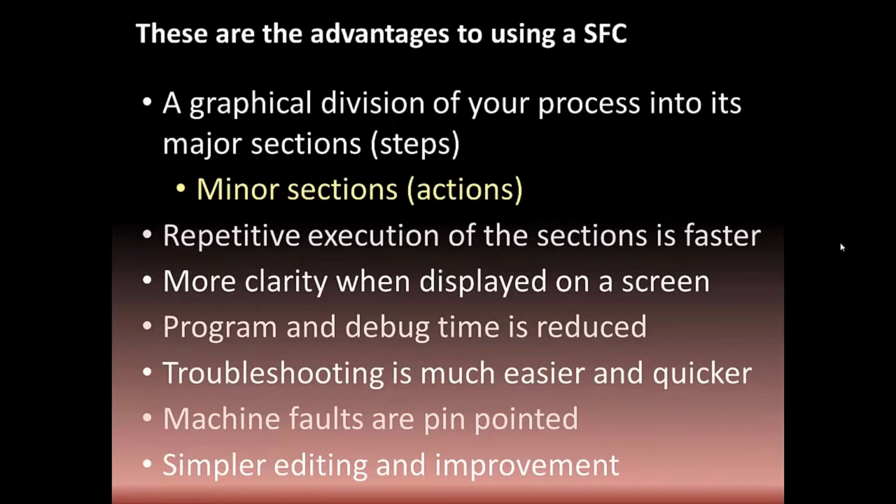That way, when the rung state goes false, all the rest of the instructions are executed, but they execute faster in a false state. With program control, using jump to subroutine and all the other program control instructions that you have, code that you don't execute, that you don't jump to, just doesn't get executed.